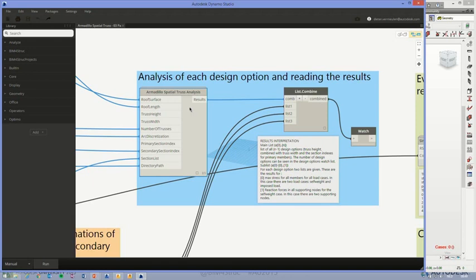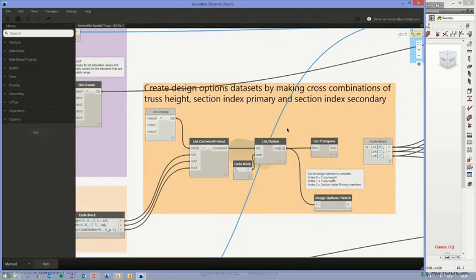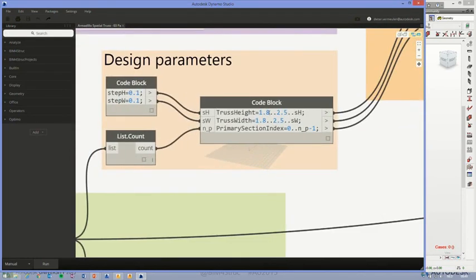So let's see this. How come we have 12,000? Well, there is one item which has a ratio which is 1.001. So that's an overstressed member, structural collapse. Okay, so therefore we have that 12,000. What about the ones which are over-designed, which is the list 0?